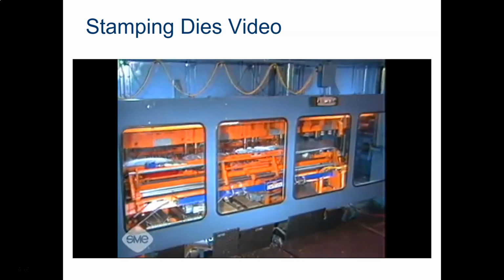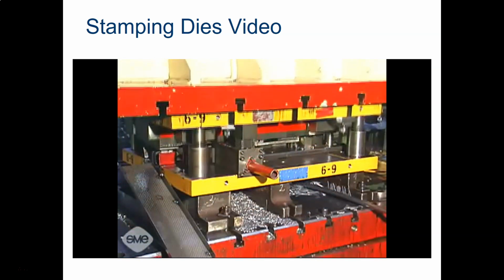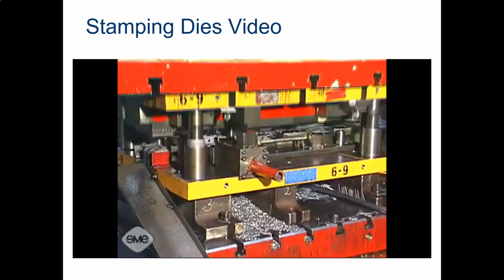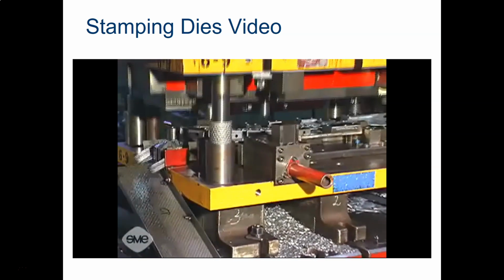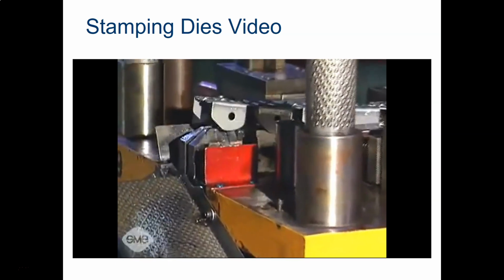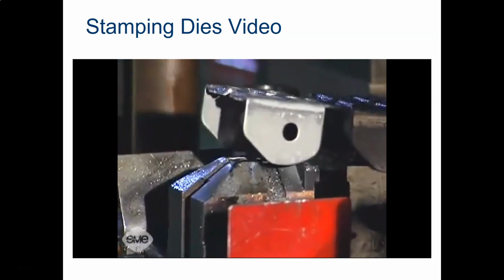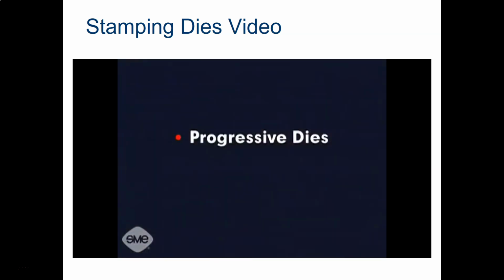Multiple station operations are done with dies that have several stations. Each station simultaneously performs a single step in a series of operations needed to complete a part. Finished workpieces are discharged with each stroke. Multiple station operations can be performed using either progressive dies or transfer dies.